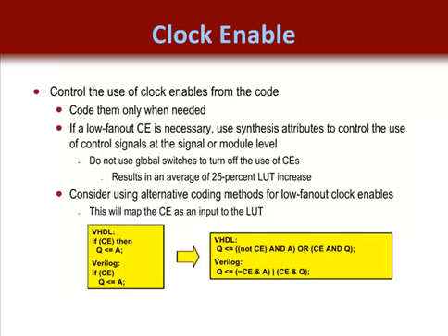A common question is, how do I control how my synthesis tool infers clock enables? Recall that like synchronous resets, clock enables can be connected directly to the flip-flop or be connected to a LUT input. The intention is that you might want to design your lowest fan-out clock enables to use a LUT input. This will decrease the number of control sets in your design. To force the clock enable signal to a LUT input, you should code it as part of the register's output, as seen in the example on the right.